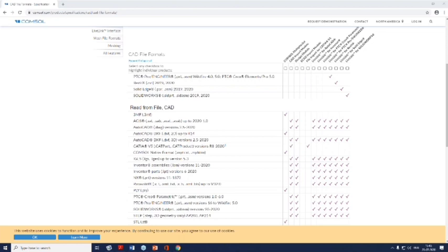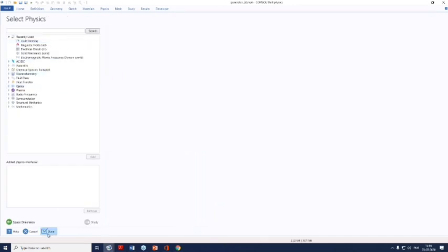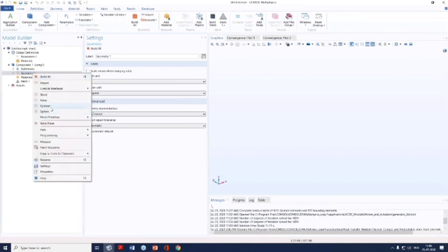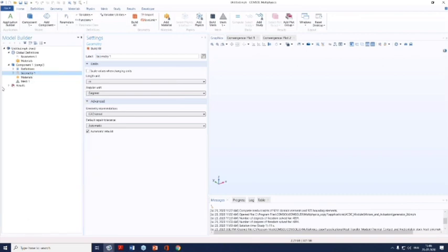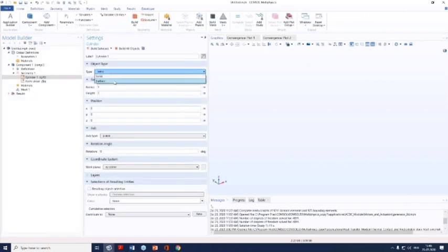What is the easiest way to create a hollow cylinder vessel? Okay, interesting question. I'll just show you. Whenever you are using any 3D primitives, either you can create them as solid, or you can create them as surfaces also. So if you want to just create a shell of that cylinder, in that case you can use this surface object.